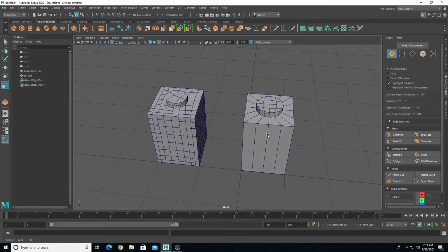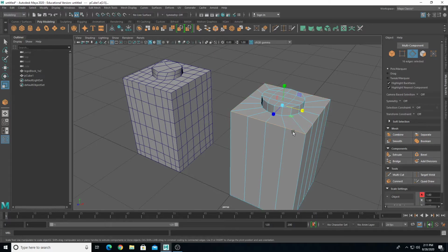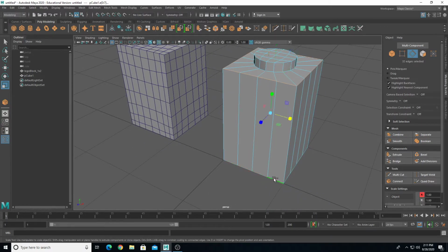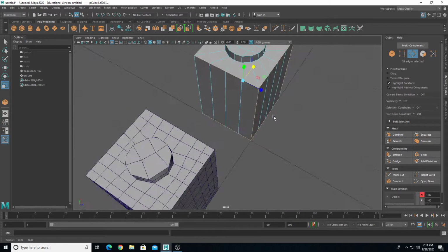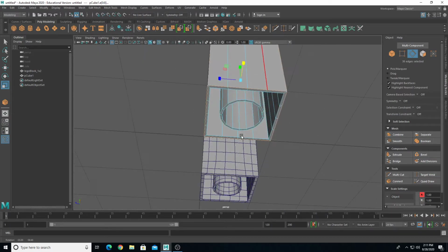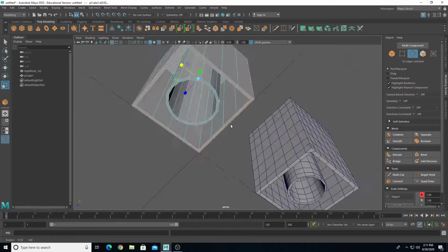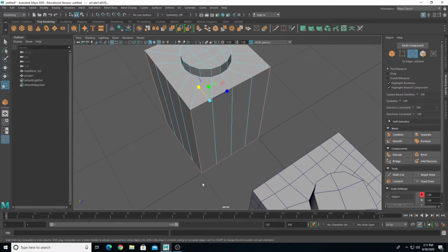All right, one final thing I can do is a lot of Lego pieces have some beveled edges to them, so I can take either one and I can go around and let's select the edge loops all the way around horizontally, and then the vertical edge lines. Maybe we'll even do that inside edge loop there. There you go. That'd be good for now.